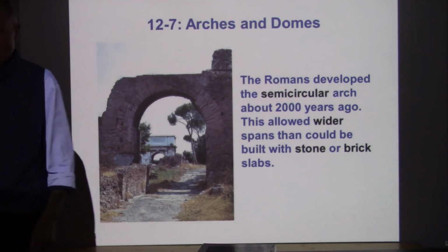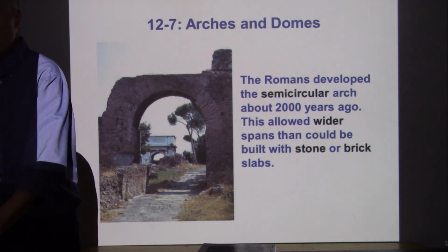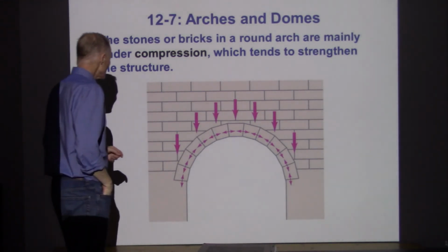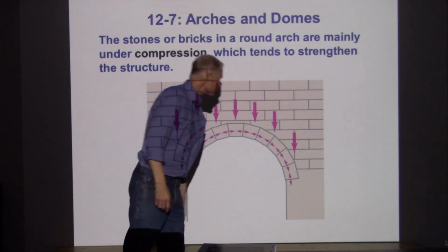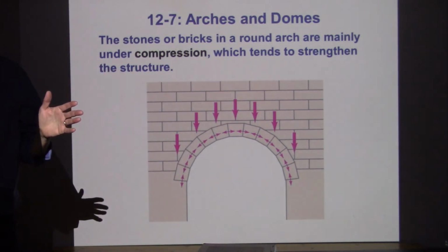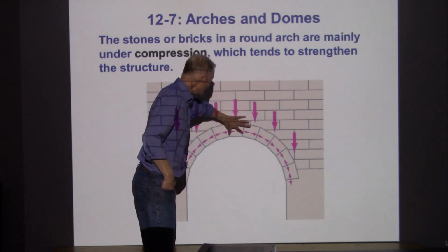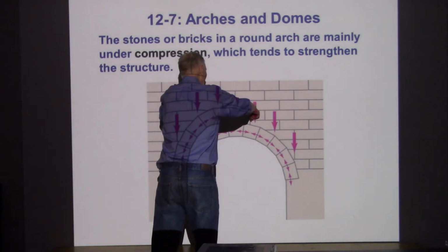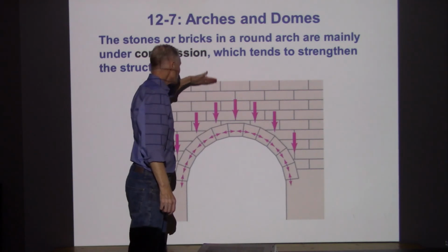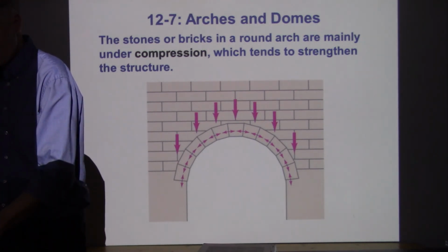And there are just so many structures, you see these, that have survived thousands and thousands of years very successfully by using a simple idea of compression. And here's the diagram that goes along with it. So with those stones, you build a wood support, and you lift up all these stones and put them in place, and then you remove the wooden structure underneath, and they stay there because they're stuck. The stone at the top can't fall because it doesn't fit through this opening. And these are not going to move out of the way for it because they've got forces acting, pushing them down also. So you build the scaffolding, you put in that arch, you build a bunch of stuff up on top, you take out the support structures from below, that must be exciting, but the stones all stay in place. So, using compression to an advantage.